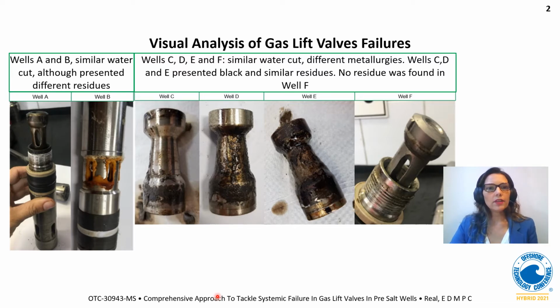So, if these are natural flowing wells, why did we use gas lift equipment? Because in 10 years we expected to need them, and it's cheaper to install them at the first completion than to spend money on a future recovery.